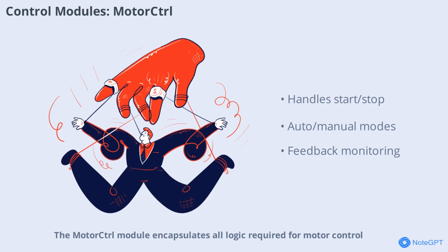The MotorCtrl module encapsulates all logic required for motor control, including start-stop commands, auto and manual modes, interlocks, permissives, trips, feedback monitoring, and run-hour totalizers.